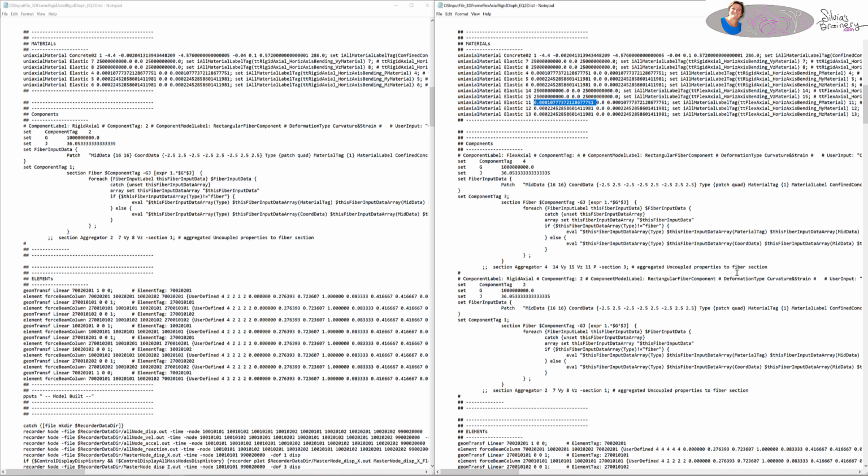So that's the material that has a very low flexibility number. It's not 0, it's just a significantly small number. And if you scroll down, you will see that I get to there. And there's where I define the section aggregator for the beam, where I have material 11 for axial force. And you don't see that on the left-hand side nor in the column. And so this is just a tiny little trick that I learned to remove PM interaction from an element without putting in an additional zero length element with no stiffness. So it's all done within the fiber section.